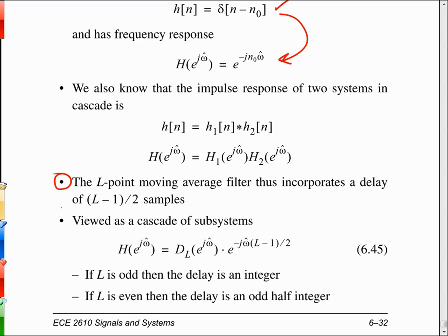is something that I have in one of the projects, and it uses a continuously varying time delay. So if you can send a signal through a time delay that changes with time, then you can create a Doppler effect on the signal, because basically you can stretch time out and then press it back together again. And we know what Doppler sounds like when we hear a siren or a train horn. As it comes at us, it gets pressed, so it goes faster, and then when it goes by, it stretches out and it goes slower. So with this gadget in software, you can create some interesting special effects, all under software control.